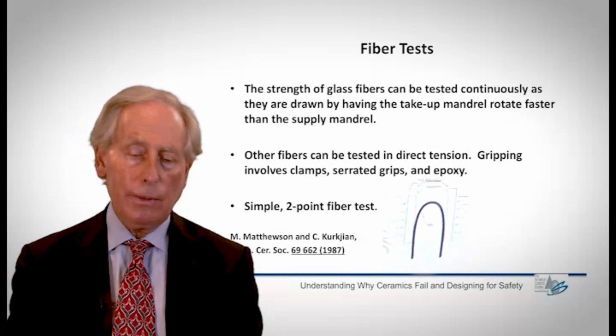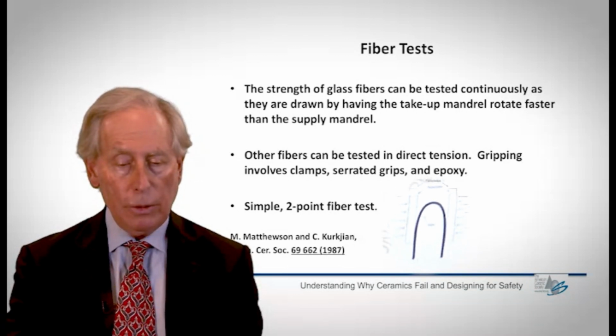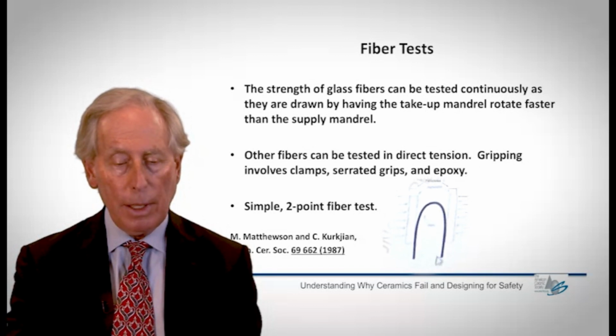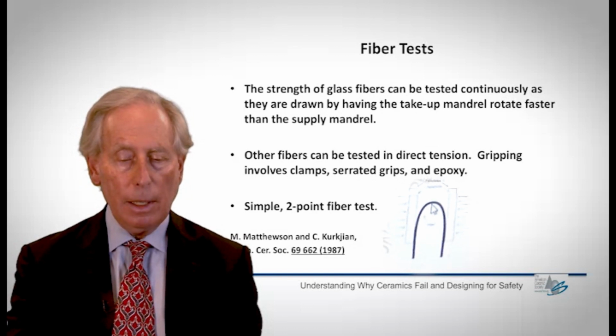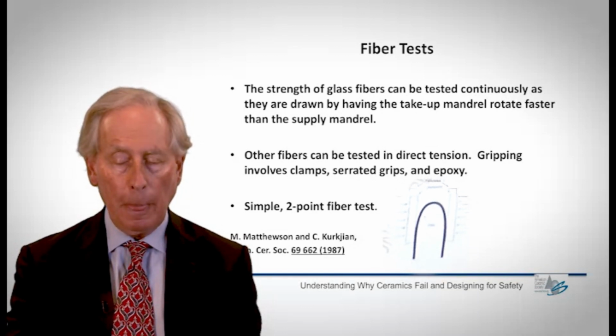But you can also test fibers in direct tension. One of the interesting ones is what is called the two-point fiber test, where you bend the fiber within a constrained cavity, such as you see here. This is a good reference to how one calculates the strain at the point of the fiber down in here, and it can give you some idea then of the fracture strength of that fiber.